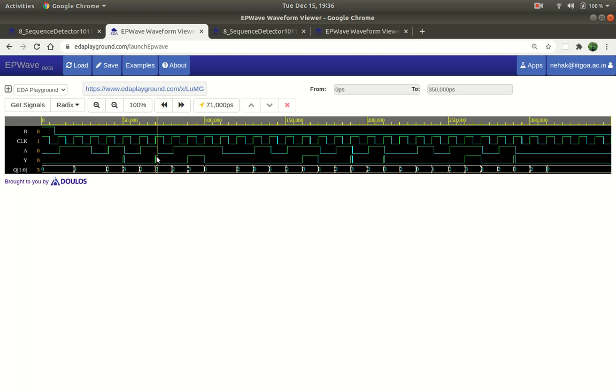This is the issue with Mealy-type designs, where you have a direct path from the input to the output going through combinational logic. So we see two small glitches. This is happening because the input is slightly delayed. For a short period after the clock edge, the input value is still 1. It takes a little time for it to go to 0. So actually the input is 0 in this clock period, so from state 3 with an input 0, you should be going next to state 2.